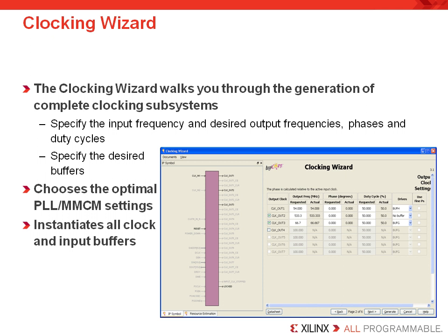This simple table allows customers to enter their desired clock frequencies and phase relationships. The wizard calculates the required attributes, that is your multiplier, divisor, and output values, to produce the desired clock signals. The wizard even allows you to select the type of buffer for distribution of your clock signals. And the wizard will then produce an instantiation template and automatically associate it with your ISE project.